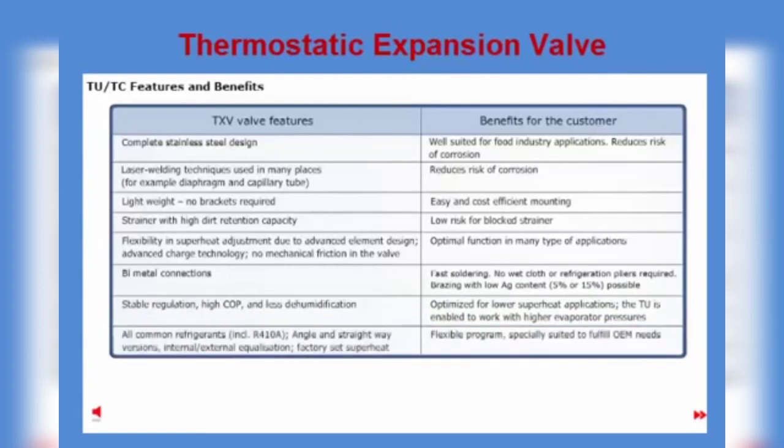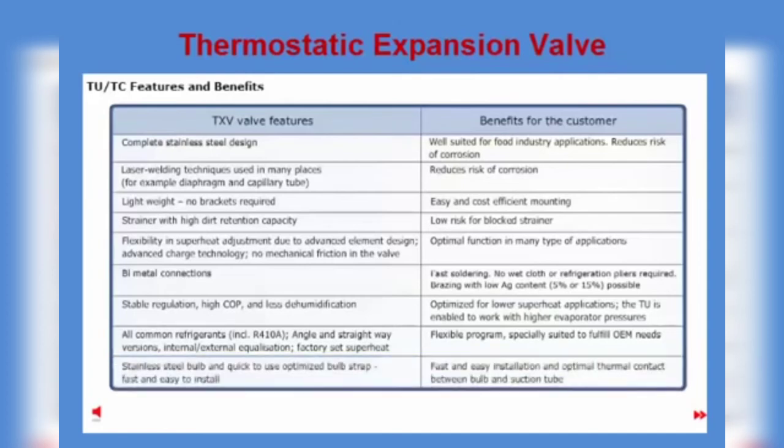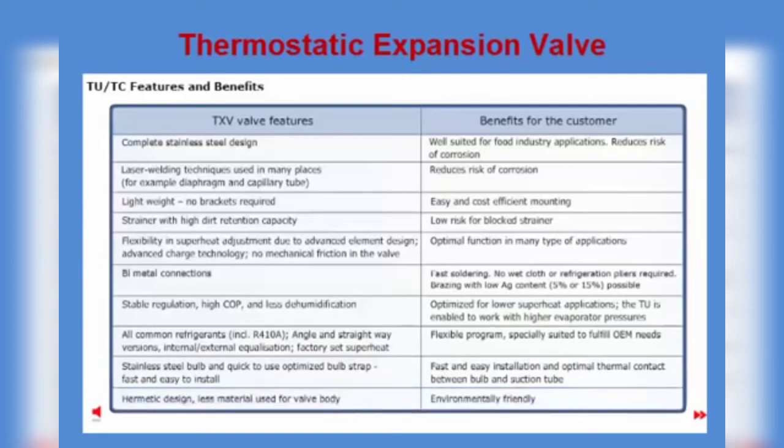Works with all common refrigerants, including R410A. Angle and straightway versions, internal or external equalization, factory set superheat. Stainless steel bulb and quick-to-use optimized bulb strap, fast and easy to install. Hermetic design, less material used for valve body.